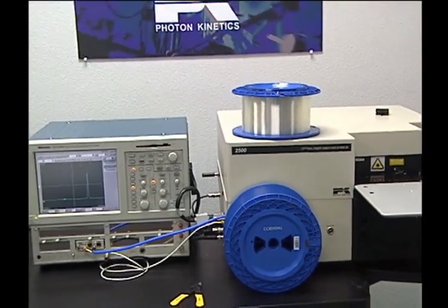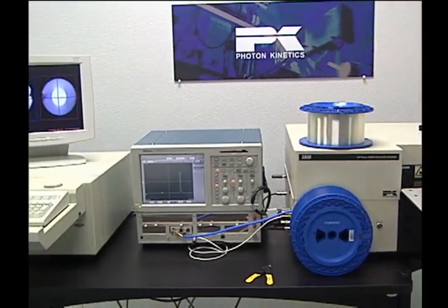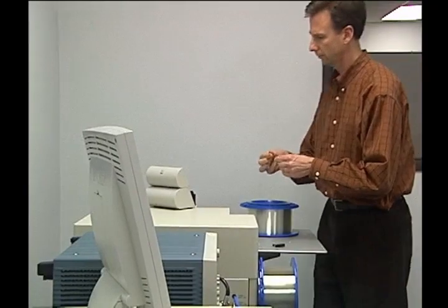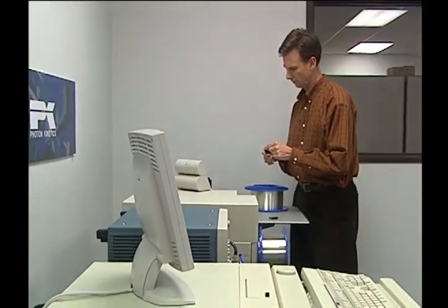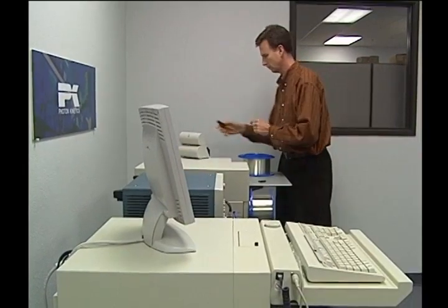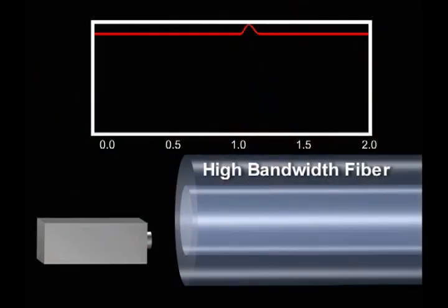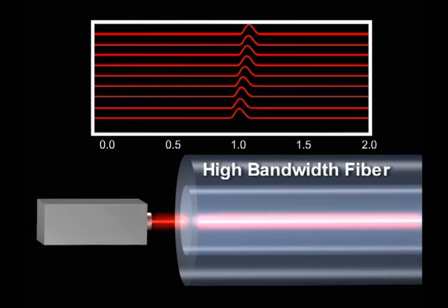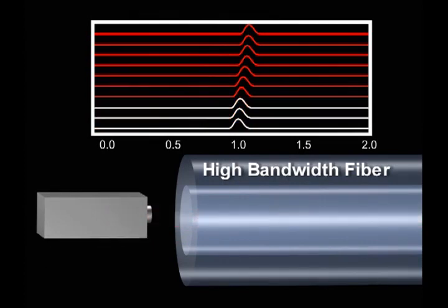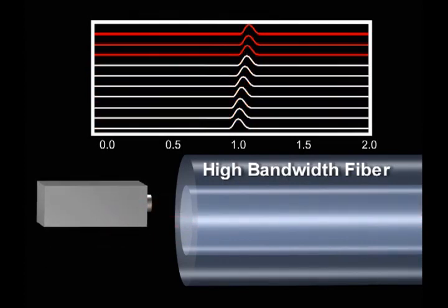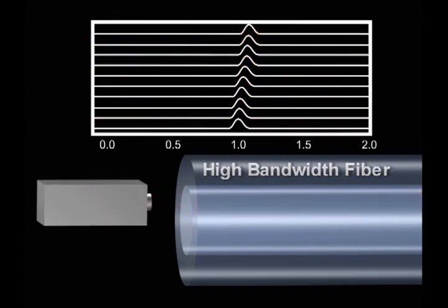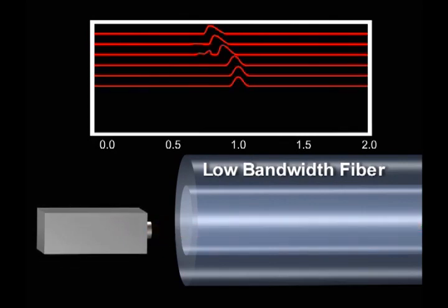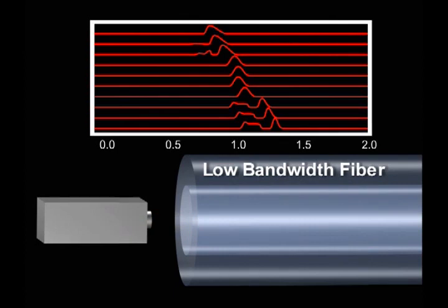The extraordinarily high bandwidth requirement drove yet another change in measuring EMB. As mentioned previously, traditional bandwidth measurements involved a quantification of pulse broadening in the frequency domain. In order to understand high-performance fiber EMB, manufacturers employed a familiar tuning tool that measured differential mode delay, or DMD. DMD is a measurement of pulse broadening between individual mode groups in the time domain, where modal dispersion is quantified in seconds rather than cycles. This hyper-accurate measurement gives a roadmap of a fiber's modal dispersion, which can then be mathematically translated back into EMB for any standards-compliant VCSEL.